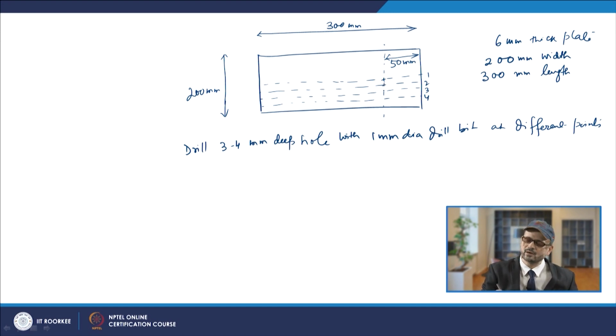Now in these holes you are embedding the hot junction of an alumel-chromel thermocouple, and these are filled with high temperature brazing material using oxyacetylene welding.